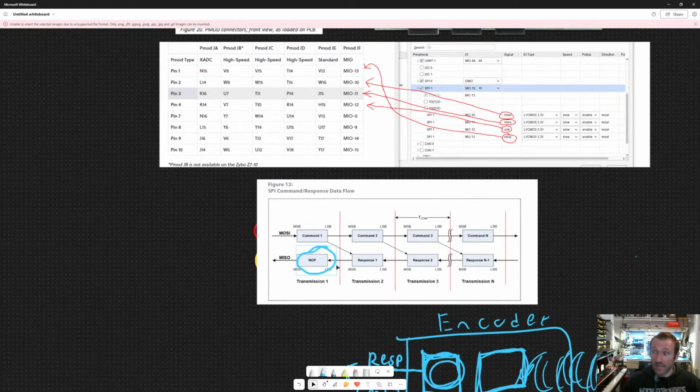And we're getting some reasonable data. It seems to be making sense for the most part. And I think we just figured out why it's having this sporadic behavior with reading the angle. I think it's because of the parity bit, so I need to remove the parity bit from that. So good progress. I'm gonna end it here though.